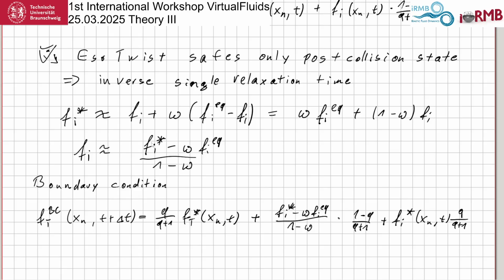So in Lattice-Boltzmann, you do not integrate the stress because you can directly compute the momentum exchange with the surface. This is extremely simple in Lattice-Boltzmann. This is why we don't bother that much that we don't know the stress.